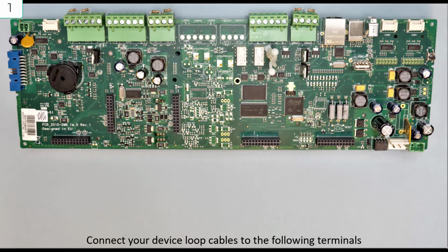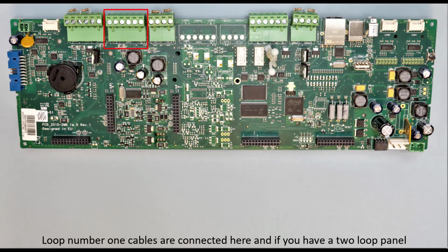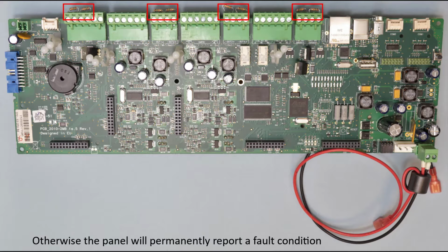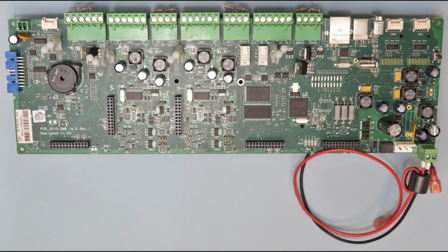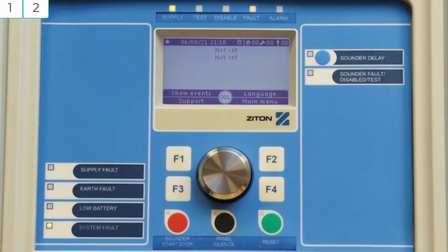Connect your device loop cables to the following terminals. Loop number 1 cables are connected here, and if you have a 2-loop panel, then the second loop is connected here. If you are not using the onboard inputs and outputs, fit the 15K resistors to the terminals, otherwise the panel will permanently report a fault condition. Now connect the main supply and batteries to the fire alarm panel.